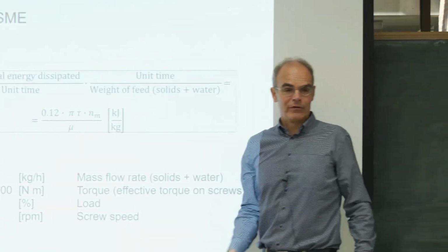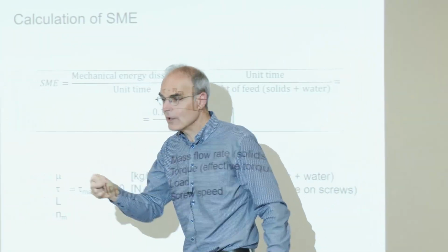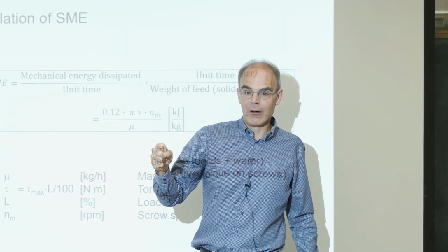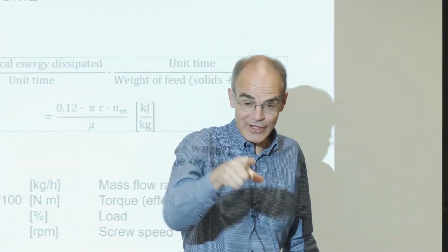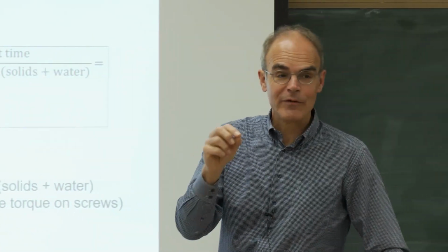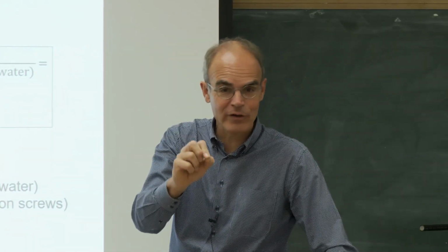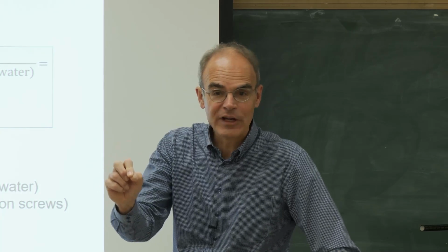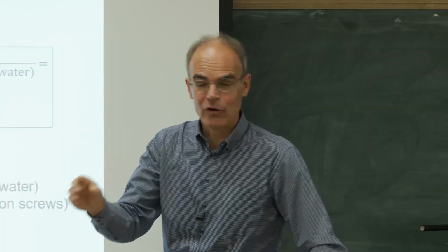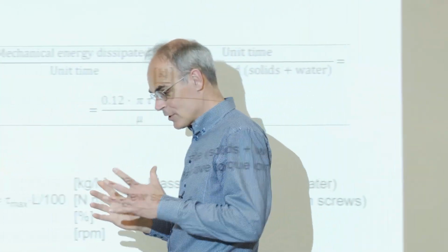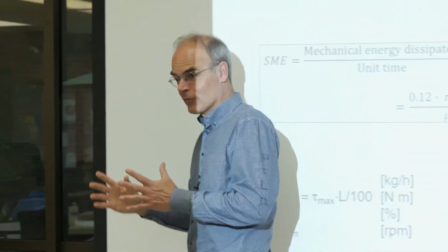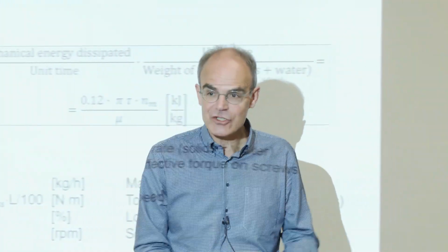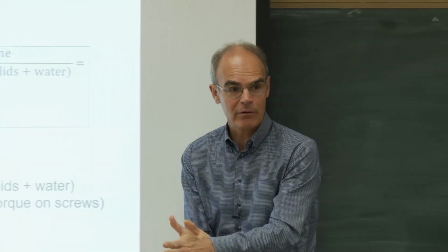Why is this so important? What is that energy doing on that material? It heats up, very good, so it's dissipated. But what's happening with that protein or that starch that I have in that system? We're shearing it. So we're shearing, and that's where that whole extruder is a thermomechanical conversion. We're shearing that material. So we're putting that energy in over the screws, and we're shearing that material.